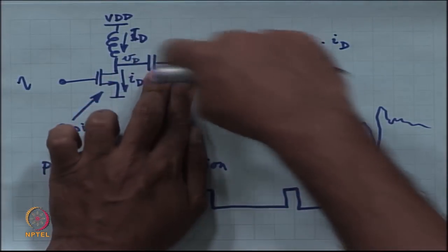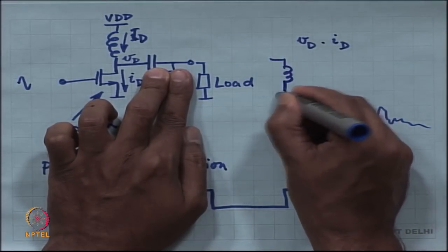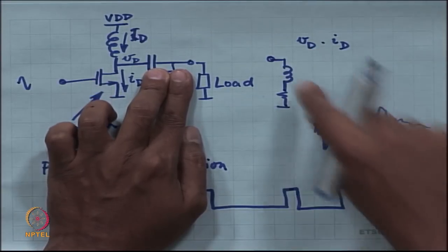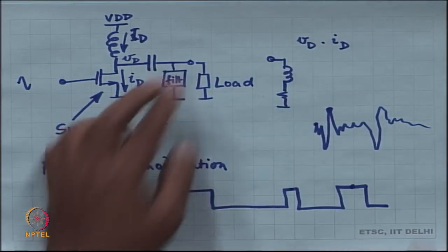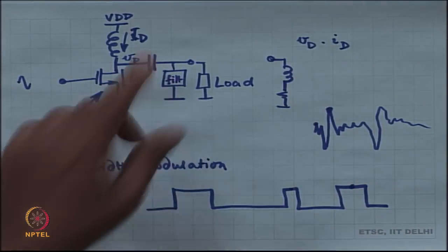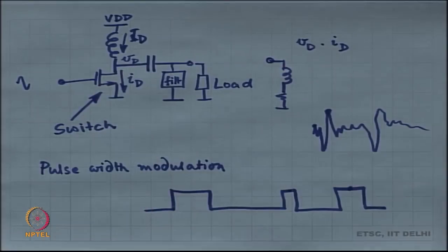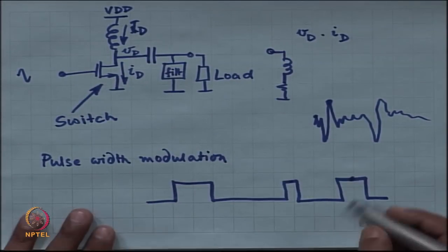Alright. So, this audio speaker can be modeled as an inductor in series with a resistor, right. It is not a pure resistor, in which case you have got L, C, R in series. Now, you play with the C value and you make sure that it is a nice filter and cuts out all the signals that you do not want. Okay. You could also remodel this as L in shunt with R, right. So, a lot of possibilities are there.